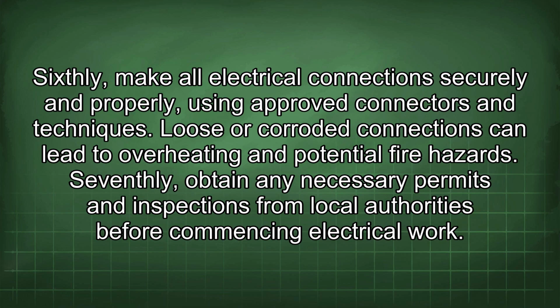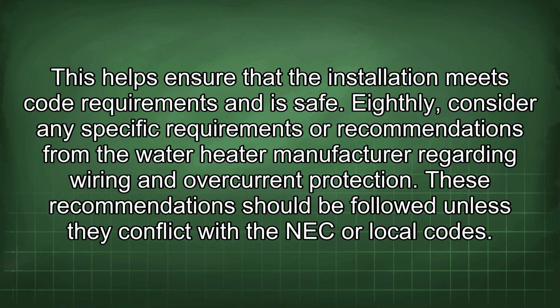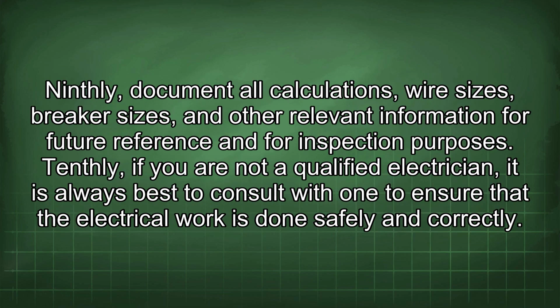Seventhly, obtain any necessary permits and inspections from local authorities before commencing electrical work. This helps ensure that the installation meets code requirements and is safe. Eighthly, consider any specific requirements or recommendations from the water heater manufacturer regarding wiring and overcurrent protection. These recommendations should be followed unless they conflict with the NEC or local codes. Ninthly, document all calculations, wire sizes, breaker sizes, and other relevant information for future reference and for inspection purposes.